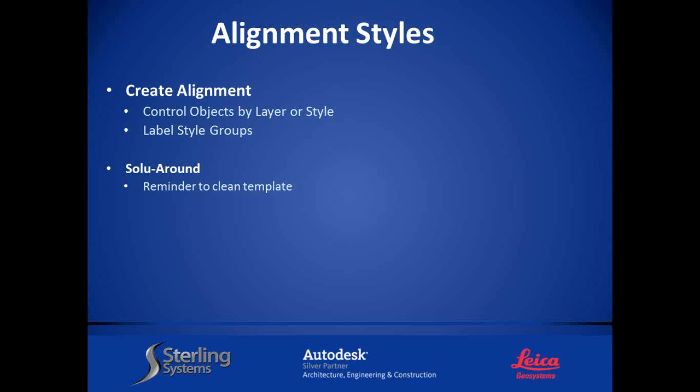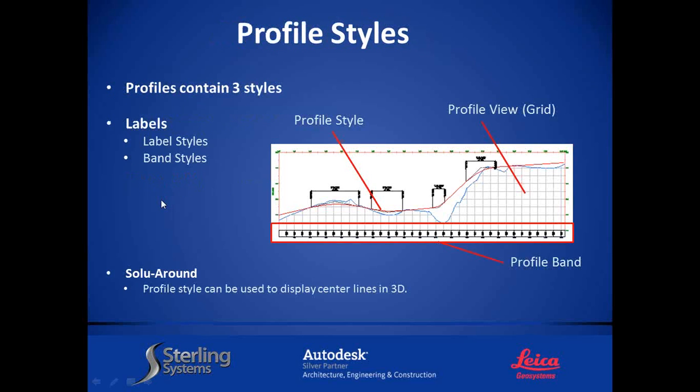So the little round I forgot about was cleaning that template, and I'll try and talk about that a little bit later on. But to make sure everything was on, after you delete all the layers, you have to do a purge and delete the reg apps to clean up that template. So it does establish everything back in layer 0.